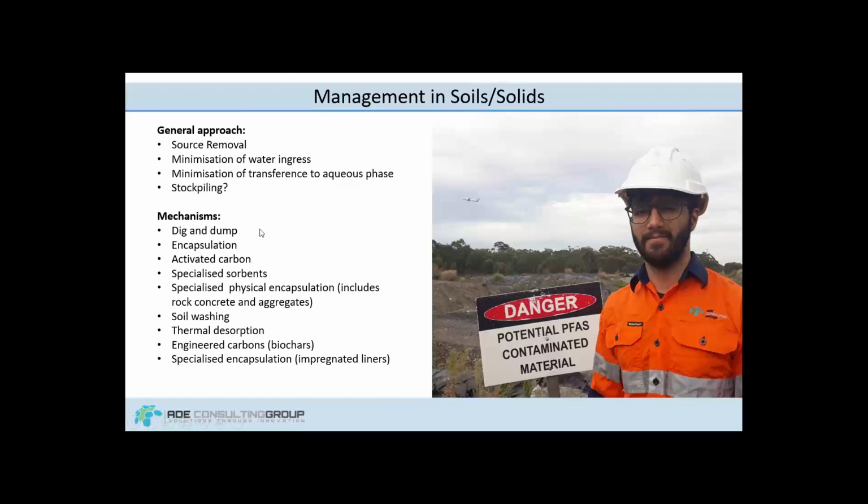So what mechanisms have we been using for managing this? Typically, dig and dump is a common practice, digging material out and sending it to a landfill for off-site disposal. On-site encapsulation, so using liners and impermeable barriers to separate PFAS from water tables or from rainwater ingress, which can be effective. How long-term a solution that is and how it manages leachate basically brings in various shades of how effective it can be.